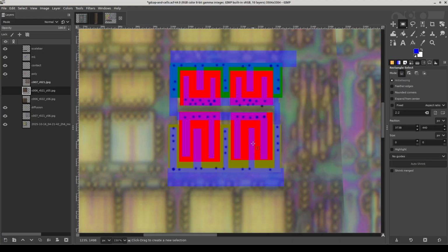And if we look also at the metal pattern, there's this interdigitated finger structure, and this piece of metal here, this is at VDD, but it's not actually connected to anything. There's no contacts here. However, this piece of metal is grounded, and these fingers are relatively closely spaced, so we have fairly high capacitance in plane coupling through the dielectric between this power and this ground.